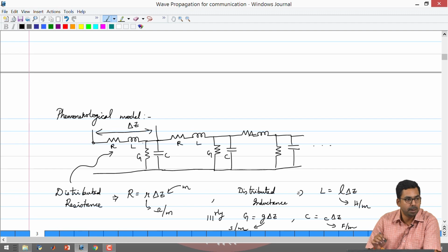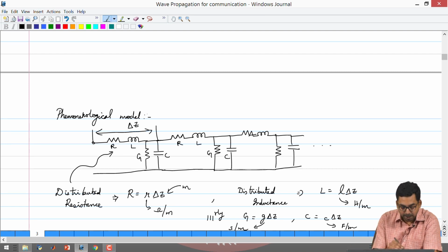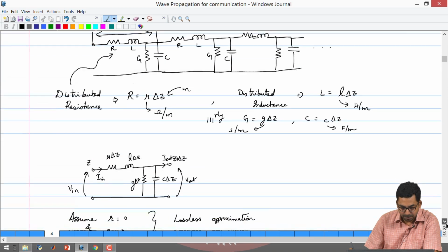In the case of a board, you will have traces on top of the board and a ground plane at the bottom of the board, and there is a dielectric in between. So, you will end up having some capacitance. So, the capacitance is connected this way, and the capacitance is not going to be the only component connected across, because the dielectric is not going to be ideal. You will also have some small amount of current trickling between them. So, that is modeled as this. So, this repeats everywhere throughout the section of the wire, and what we are now doing is known as a distributed model of an interconnect or a transmission line.